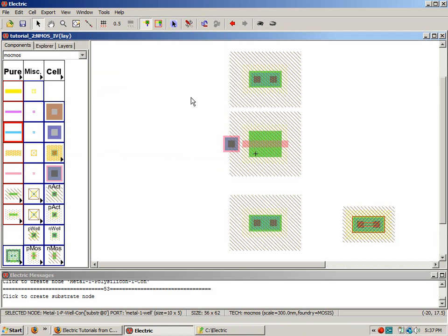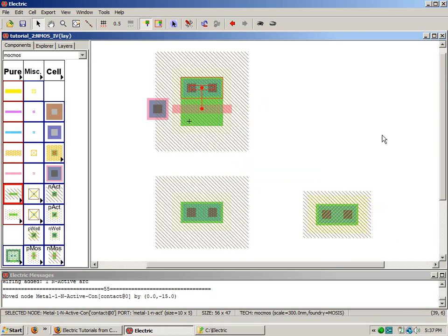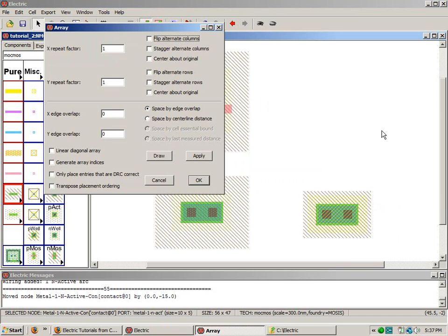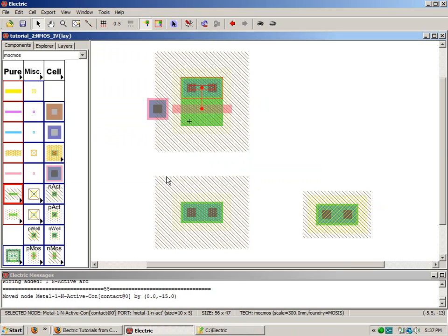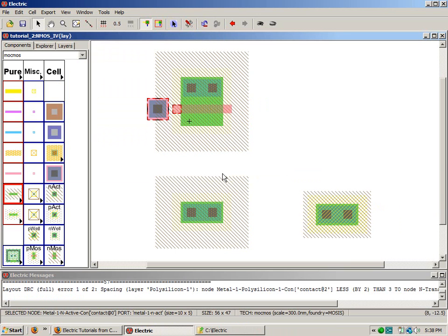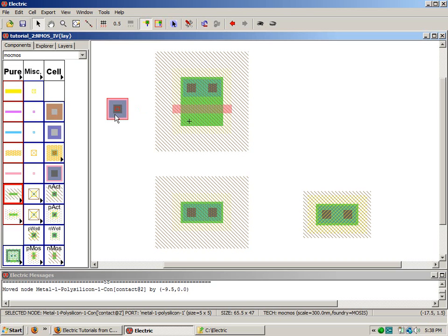Now we're ready to connect things together. So we'll left click here, then go up here and right click. So notice we're using this arc right here, which is inactive. Okay, we just connected. So we can do several things at this point. We could just move the arc down here till it's adjacent to the MOSFET, hit Fit, and then press F5. Whoops, wrong, that was F6, F5. 2 errors, let's see what they are. Oh, I connected those up, so let's move this away. Now let's do F5. Okay, no errors. And so this is the drain of our device, moved it down.